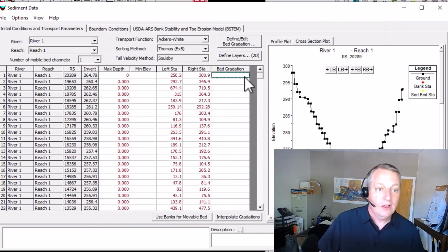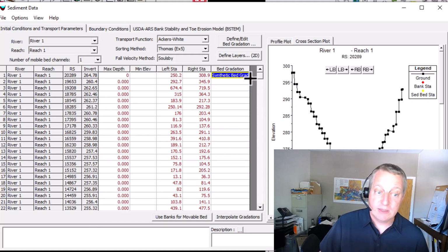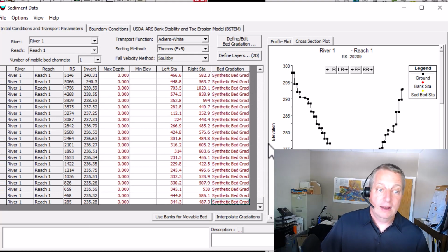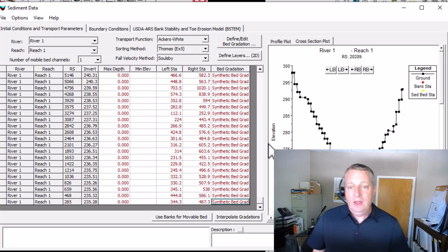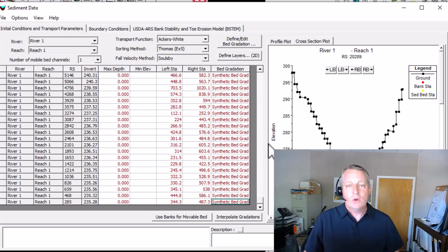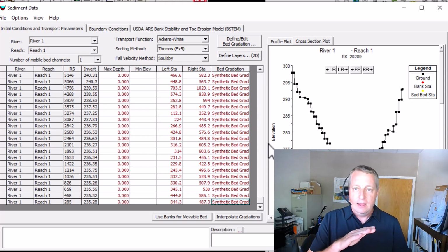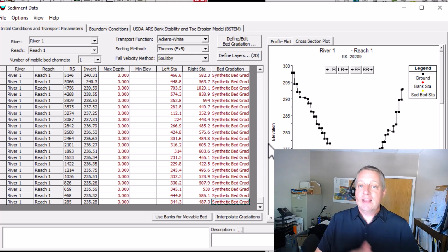Okay, so then I'll go in and I'll just select that here. And then if I hover over this and pull this down, that populates. Now, this is the only kind of model where that doesn't matter. In most other models, this is one of the most sensitive parameters. So I don't want you to get from this video, hey, that doesn't matter, you can make it up. But because we're doing a reservoir model, which is mostly deposition, but we're only allowing it to erode the sediment deposits, it's only in that case that this is not a sensitive parameter.